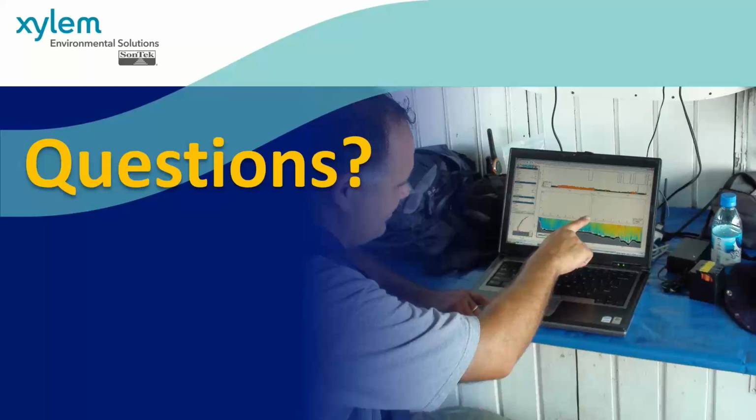That said, if you have GPS connected, you do get location and depths once per second. So you can map out the bathymetry, you can map out your cross-section using the ADCP for use in stage area discharge rating. And then you can also use multiple cross-sections collected by RSQ or River Surveyor Live to create a bathymetric map by just using the location and depth data.